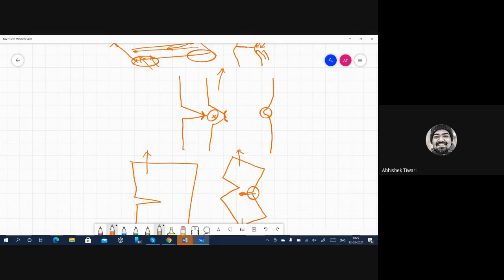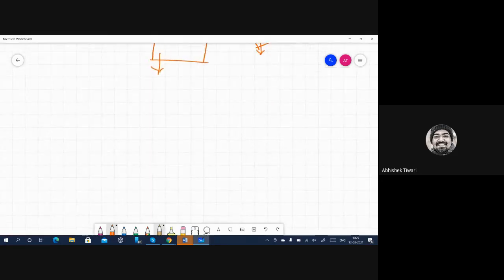And that constraint can be explained in terms of hydrostatic tension. Hydrostatic is like a pressure, and it means this thing is being pulled in all directions with an equal amount. So where will this go? Nowhere. It will have to be compromised. So if this thing is high, then material is under too much constraint. If this thing is low, material is under less constraint.